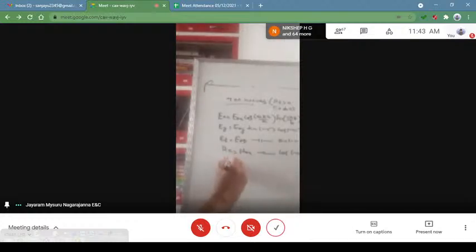Hy is equal to H naught y, and it will be a cos sine function. And finally, Hz is equal to 0, as we have already mentioned. Ez is non-zero, Hz is 0 for TM waves.